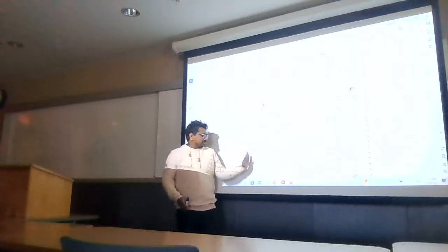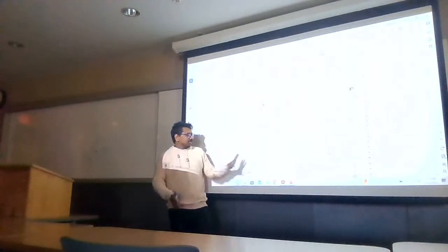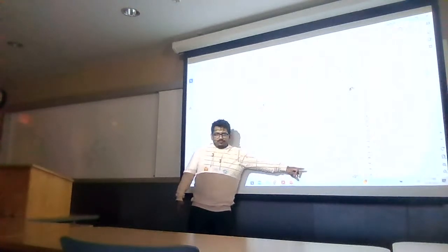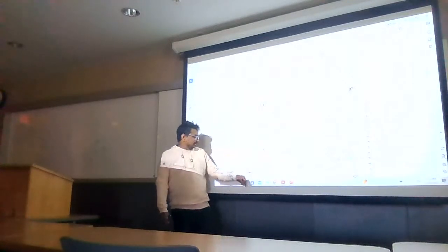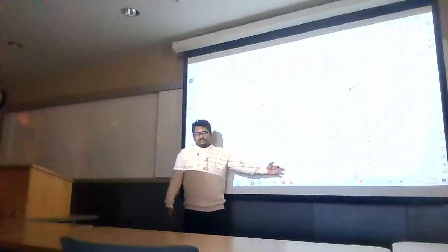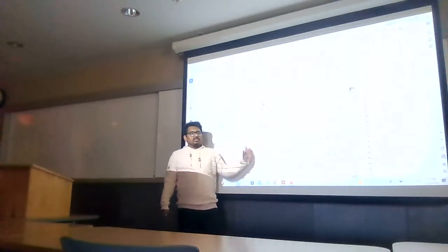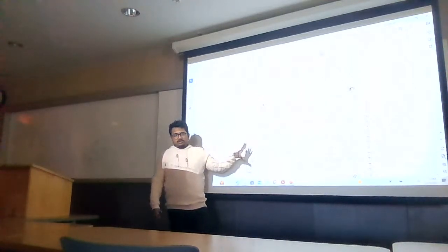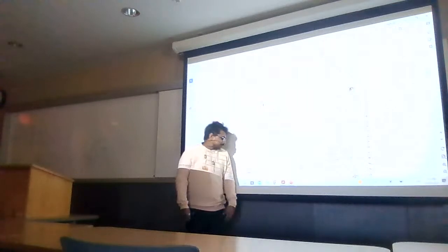So this characteristic graph depends on which circuit you are designing, and you have to find the accurate voltage of VDS where my transistor operates in saturation. Let's say it is 800 millivolt. You find that at 800 millivolt, your transistor is in saturation. Then you have to fix your VDS. You remember I fixed a VDC voltage there. The VDS is 800 millivolt.